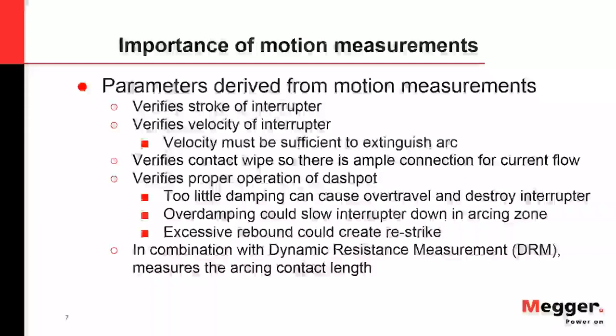You can have something where your signal comes in late, or let's say your coil's bad, so it takes a little bit longer to trip. But as long as it releases that trip latch and that spring or whatever and that mechanism gets going, as long as you have enough velocity in while during that interruption, you're going to be able to extinguish that arc.